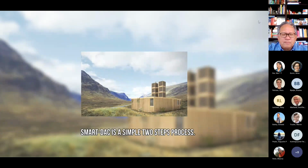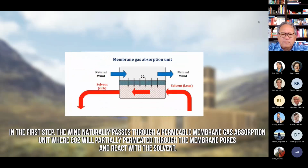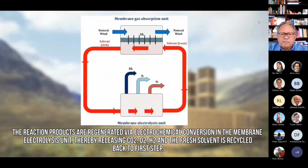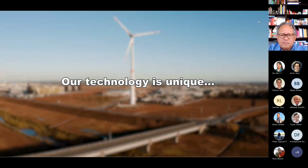Smart DAC is a simple two-step process. In the first step, the wind naturally passes through a permeable membrane gas absorption unit where the CO2 partially permeates through the membrane pores and reacts with the solvent. The reaction products are regenerated via electrochemical conversion in the membrane electrolysis unit, thereby releasing carbon dioxide, oxygen, hydrogen, and the fresh solvent is recycled back to the first step. A smart buffering strategy was adopted to synchronize the absorption step and the batch type regeneration step to ensure the overall continuous process. Our technology is unique.